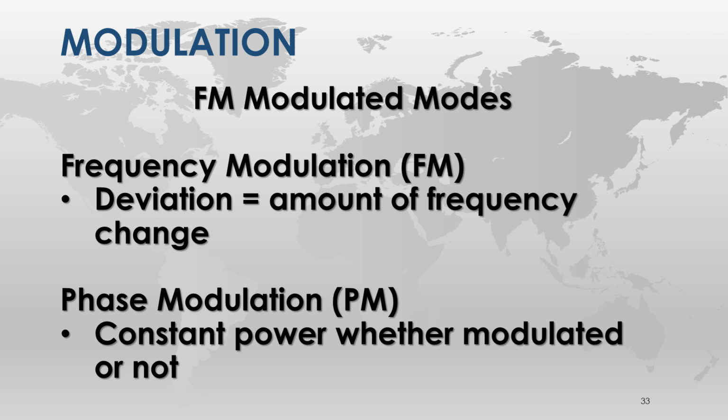Now, when you go to tune your radio on AM or single sideband, you step on the key or push the button, and your meter doesn't show you what your SWR is because there's no power going out. Your radio's not broken. It will not transmit until you modulate. So what you do is you go to CW or FM or AM. AM will give you the carrier. On sideband, there won't be anything. When I first started, I thought I broke my radio.